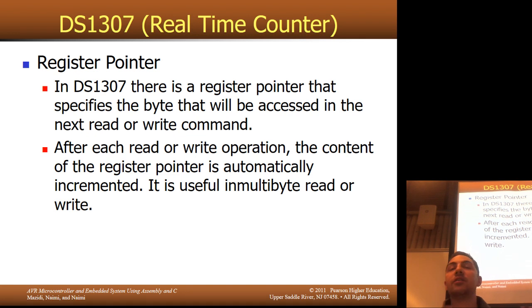First, you write to the register pointer, and then any additional writes will overwrite the time. If you want to read from a random location, random access, first you write the pointer, and then you do a repeated start, and then you do another read. Now, we didn't actually talk about how to create a repeated start condition, did we? That's because to create a repeated start, it's the same as a start condition. So if you want to do a repeated start, you just say start, the same way that you do a regular start.